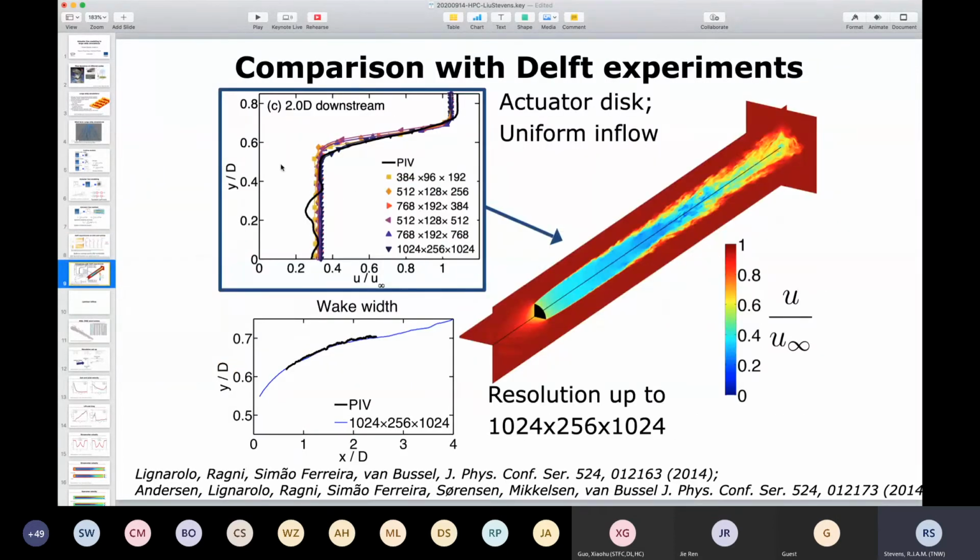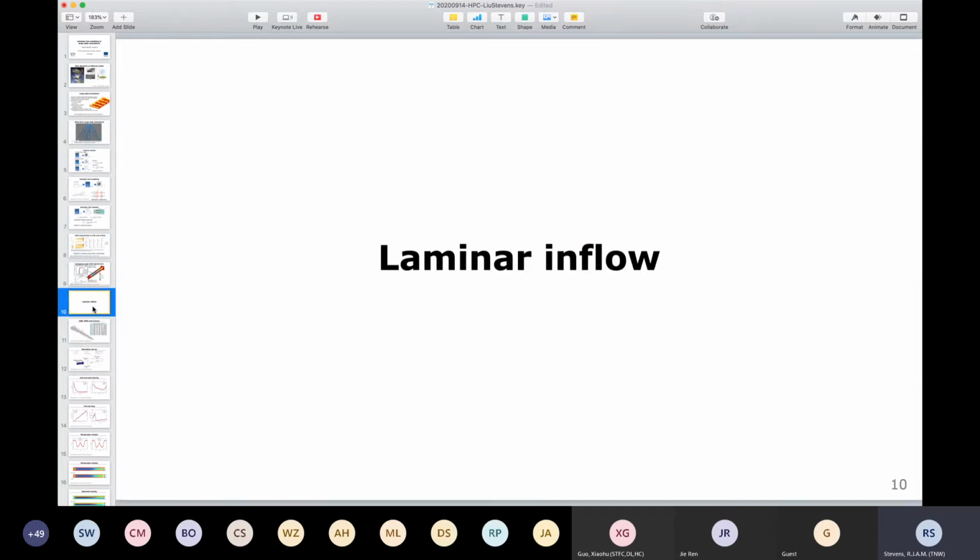This is some visualization showing actuated disk model simulations capturing the effects as observed in the experimental data. These simulations can agree very well with high performance measurements that are being performed. For these actuator line model simulations, we also want to compare against reference literature data for the NREL 5 megawatt turbine, as well as some wind tunnel data. I will present some of the initial results on that.